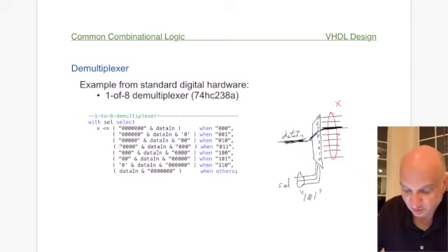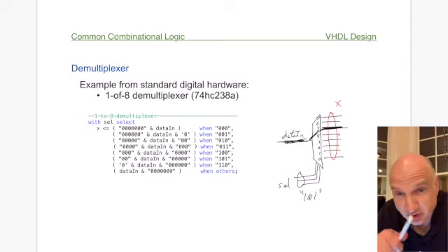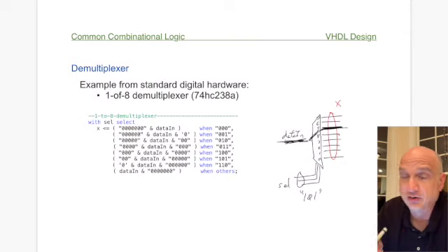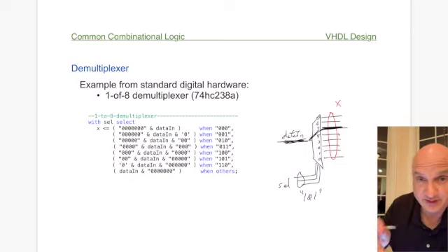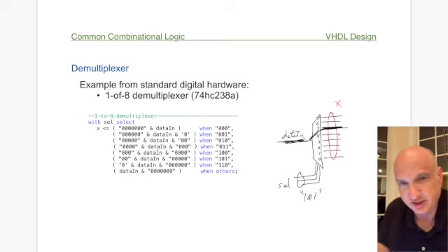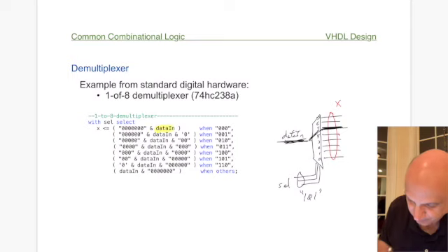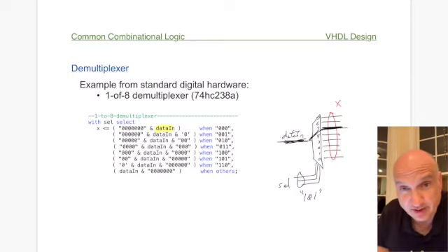So the way this would work in here is we could use yet another selected signal assignment statement, but here's a catch. We're getting to utilize our concatenation operator we talked about in the previous video. The idea of taking vectors and piecing them together. And that's very valuable here because we can put in the data in line anywhere in the output vector we want.